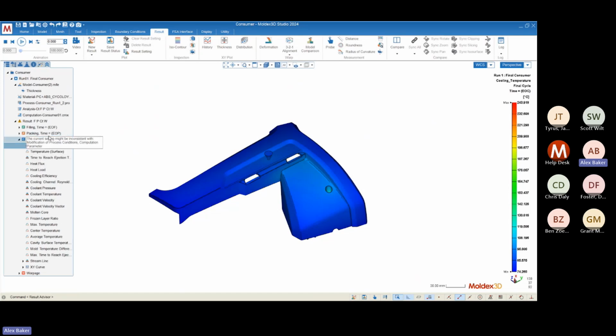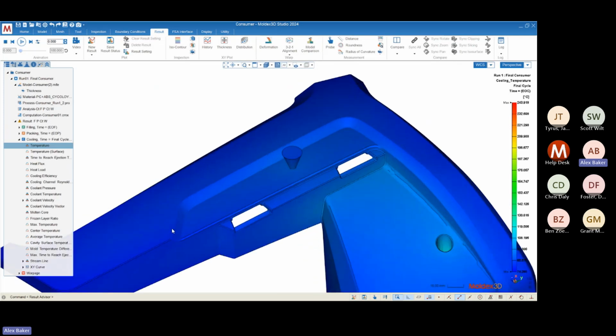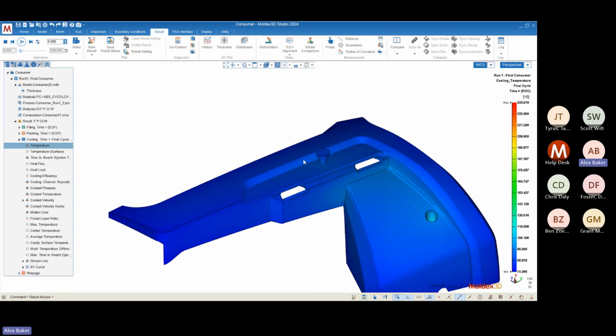All right, so all of that leads me into the warpage analysis. In the filling stage, we evaluated the temperature distribution, which is implied by how fast the material was feeding through my part geometry. We evaluated the pressure distribution in the packing stage, which allowed us to see how the packing effect, or the compression of material into my geometry, is combating the natural shrinkage effect.